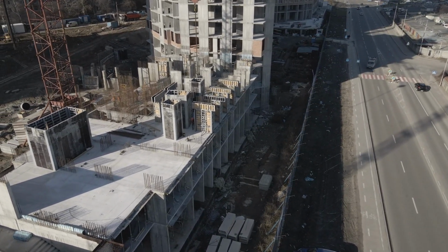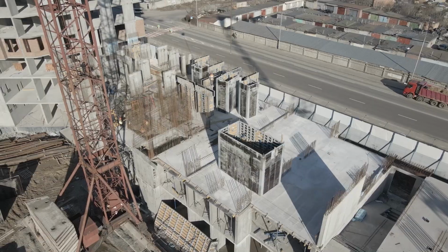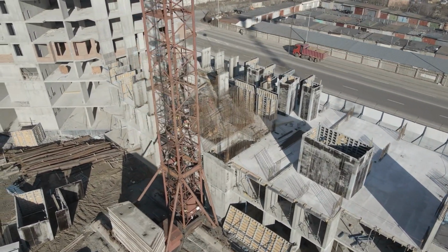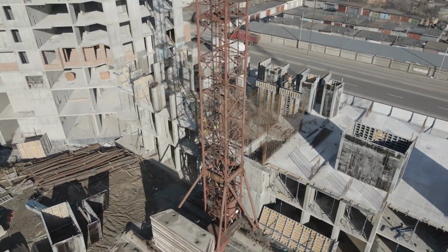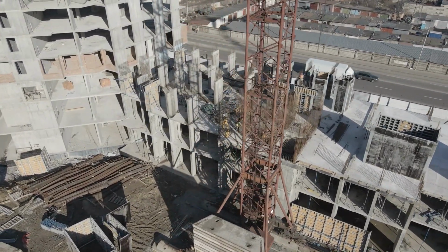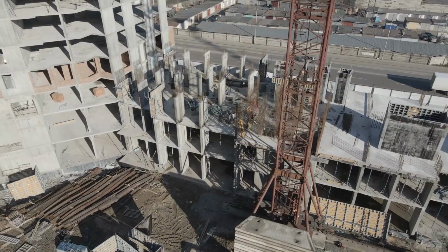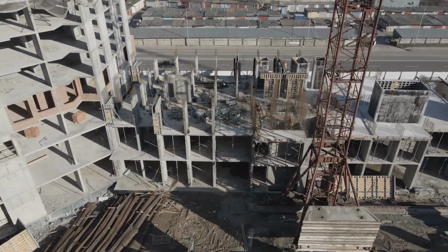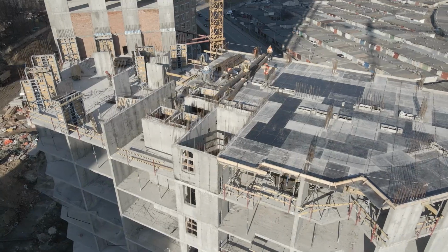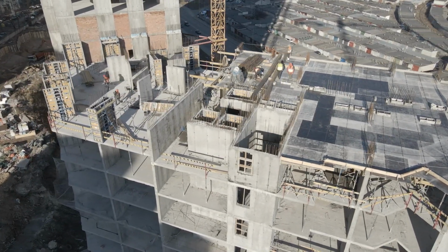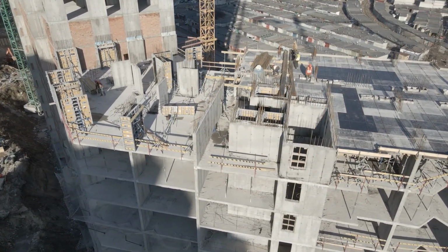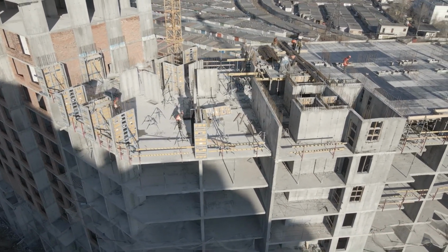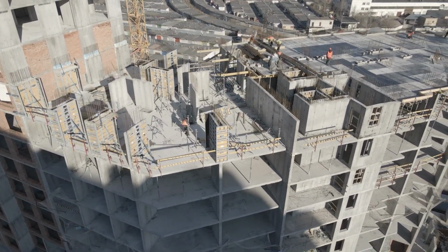Formwork and its supports keep their correct shapes and profiles so that the final concrete structure stays within the specified dimensional tolerances. They must be built to withstand the combination of self-weight, reinforcement weight, wet concrete weight, concrete pressure, construction and weather loads, as well as all incidental dynamic effects caused by placing, vibrating, and compacting the concrete. The reinforcement steel shall never be tied to or supported by the formwork.